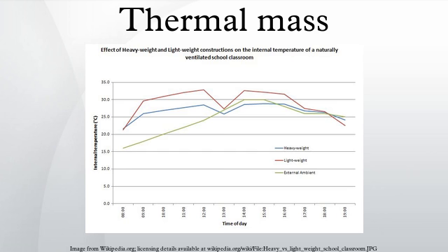The thermal conductivity of concrete depends on its composition and curing technique. Concretes with stones are more thermally conductive than concretes with ash, perlite, fibers, and other insulating aggregates. Insulated concrete panels consist of an inner layer of concrete to provide the thermal mass factor. This is insulated from the outside by a conventional foam insulation and then covered again with an outer layer of concrete. The effect is a highly efficient building insulation envelope.